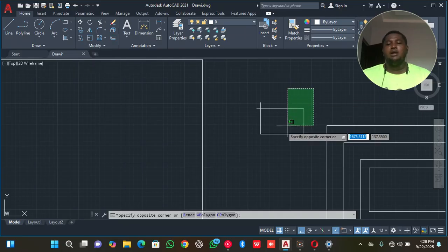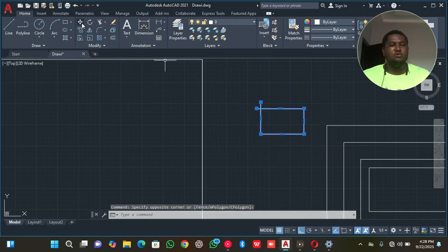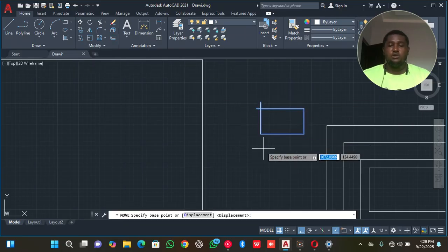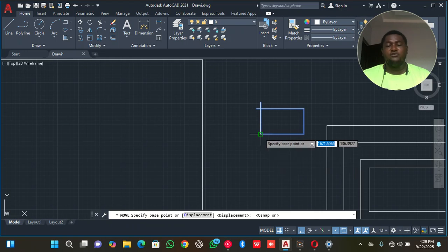So I come here, I click my drawing, I click on move. My ortho is on, which means, and if you look at the text there, first of all, turn off your OSNAP. OSNAP allows you to click on the edges of the drawing easily. Very important. It can be difficult when you're picking a circle and you want to draw a circle with an object, and OSNAP keeps making the cursor go into other areas.